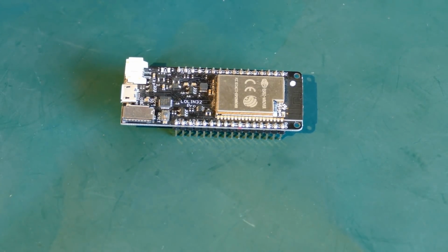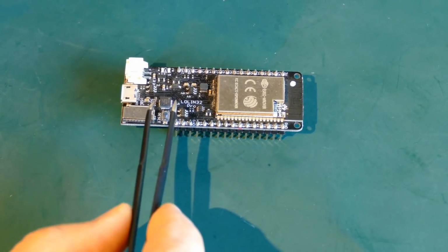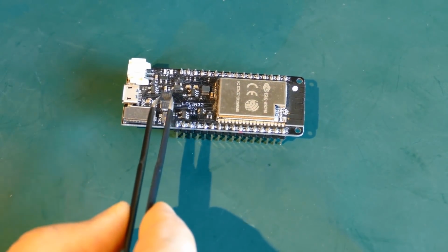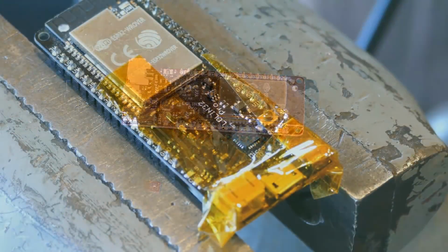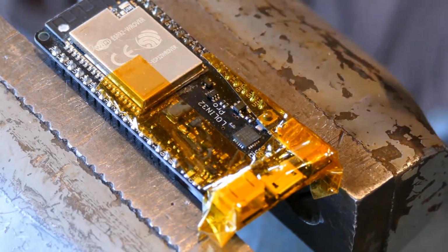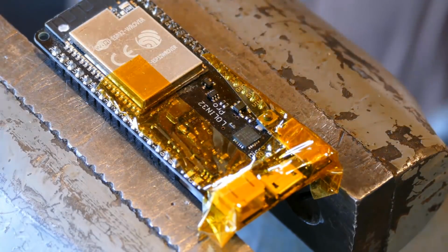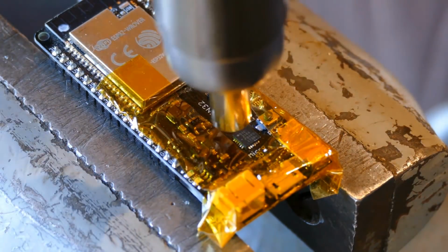By the way, there are many great hot air rework tutorials on YouTube. This video is not meant to be a how-to reflow. Depending on the results, it might become a how not to. I covered some of the board with Kapton tape so I don't melt any of the plastic parts and to reduce the chance of inadvertently blowing a small passive off.